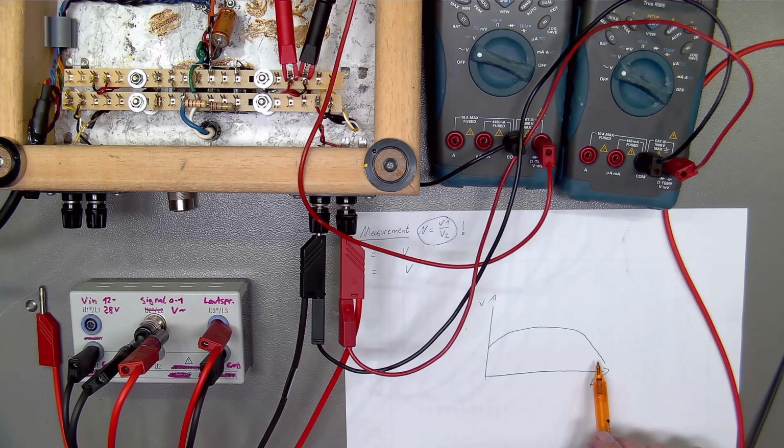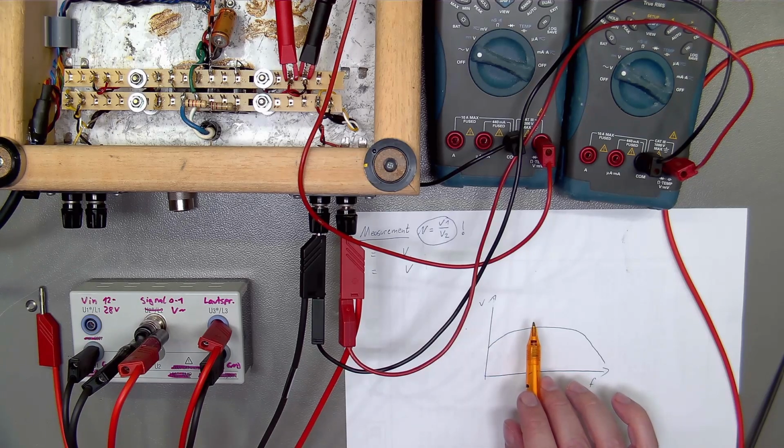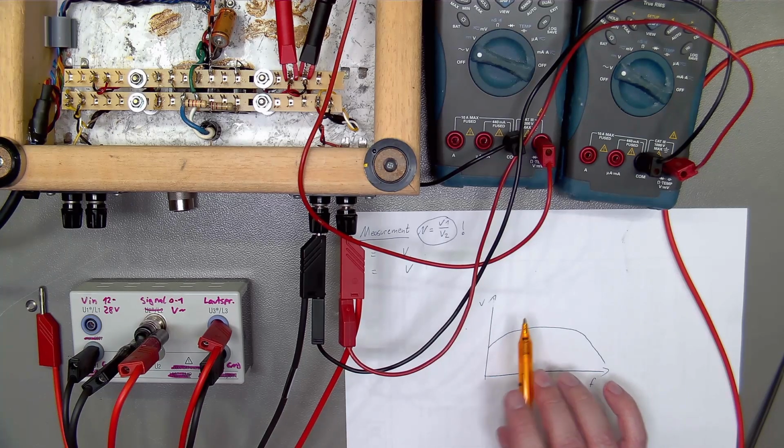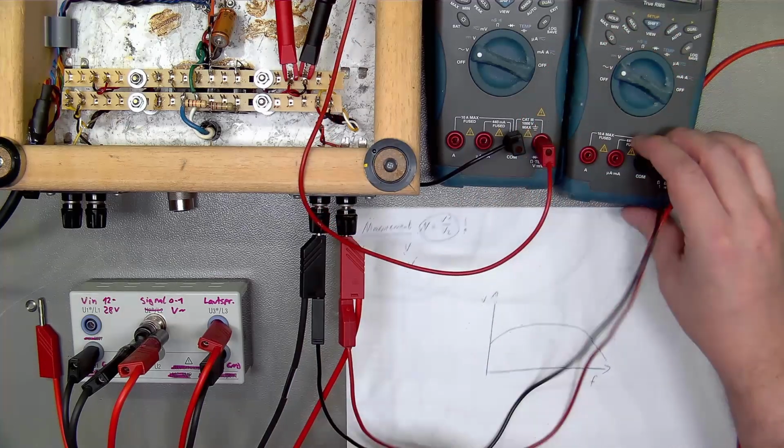So we do not want to measure with like 10 megahertz, it will probably not do much. We also want to avoid measuring at 50 hertz, which is pretty damn near this beginning part. So we want to push it a bit further in. We could also use like 10 kilohertz, which is usually completely fine, but 1 kilohertz is a pretty standard value as well.